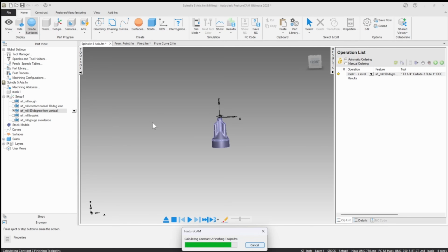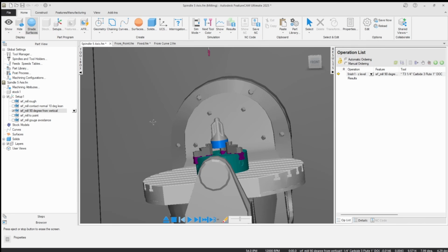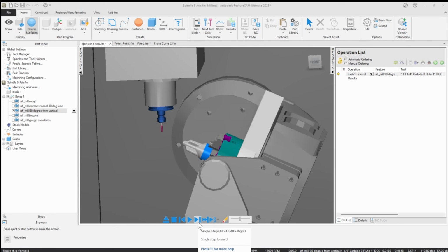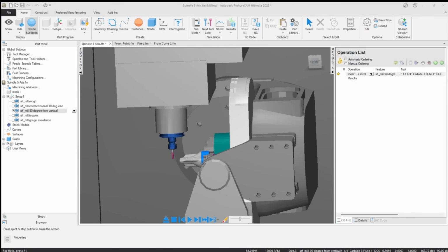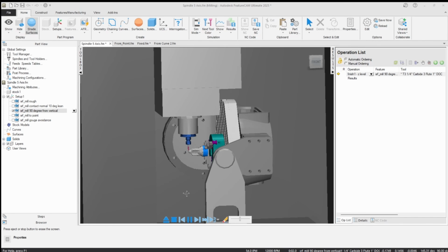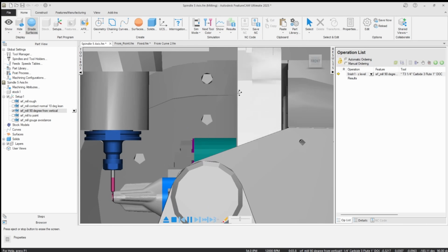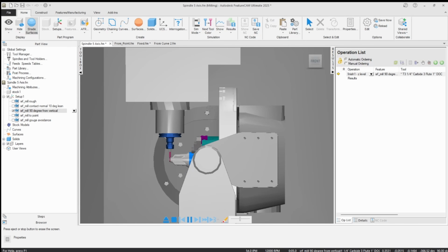We'll see that the toolpath now has the table rotate all the way over. So I'm just kind of single blocking this as we go through. So we see we get an entire 90-degree rotation, but if we were to run down, we'll see right in this area where the rotary is spinning and where this little notch in the spindle housing is kind of close that we might run into. So you can see where we're going to run down in here.